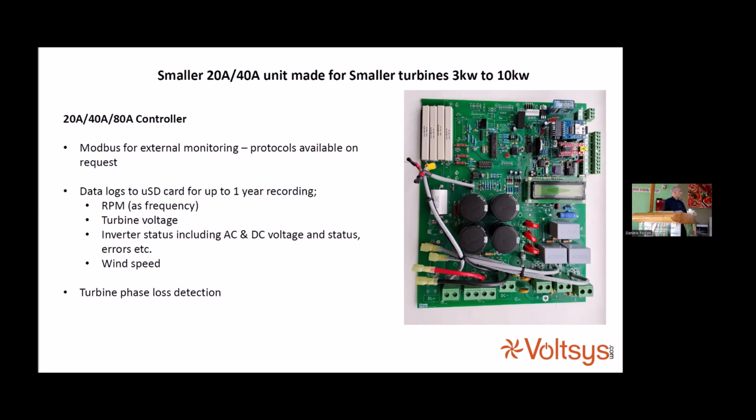Oh yeah, another thing that we can do is detect phase loss. It's quite important to detect phase loss, particularly if you're using frequency to control the power conversion by the inverter. Because if you're using frequency, the two wild AC strings that you're connecting the frequency measurement to may be working, but you could lose the third leg.